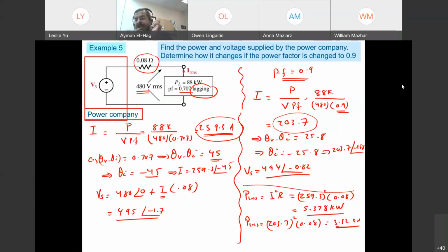Excellent, Grace. So this is the objective of the capacitor. We don't have capacitors in the home, but we add them in the network. Why? To cancel the inductive load. Because they come with the minus sign, they will cancel the inductive load. We will not be able to have a completely pure resistive load, but usually we have a 0.98 to 0.95 power factor. That is very typical by adding those capacitors.